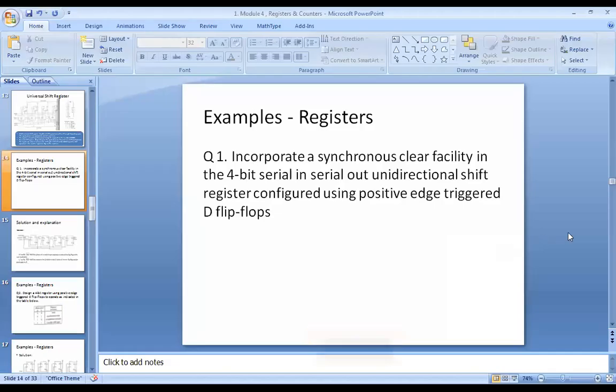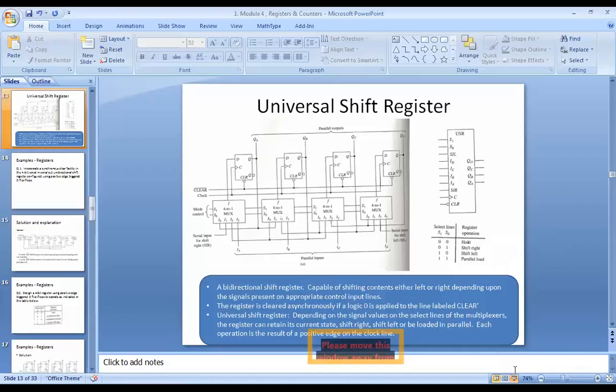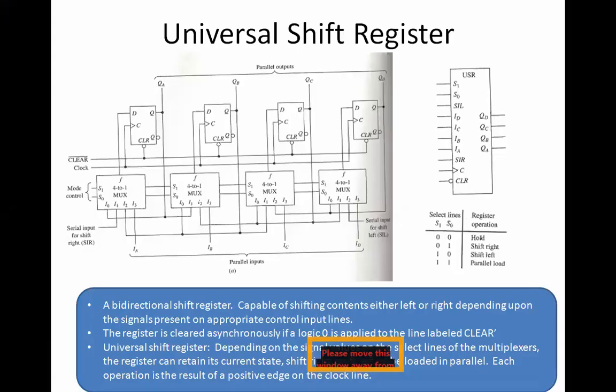So yesterday we had discussed the examples of registers, and we had looked at the universal shift register as well, right? This universal shift register can be used for multiple purposes. It can be used for hold, shift right, shift left, and parallel load operations. So based on the universal shift register concept, we can actually design any register,